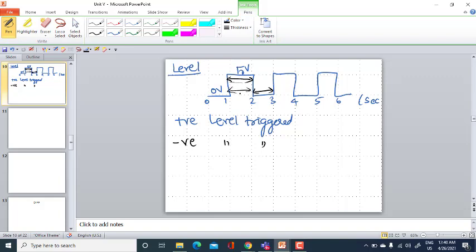or the period of the pulse is larger, maybe your on period and off period is larger. Consider this as a black box, let me consider a long on pulse. So during this, if I am changing the input rapidly, your output will also change rapidly. So you won't get a constant output. So mostly it will be good if you go ahead with your edge triggered design.